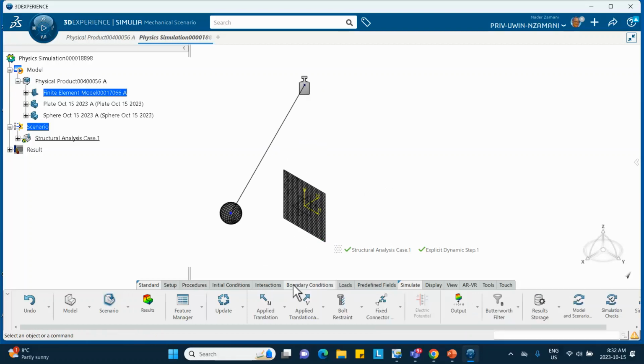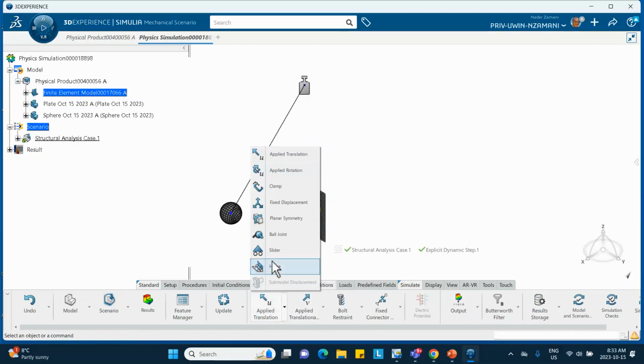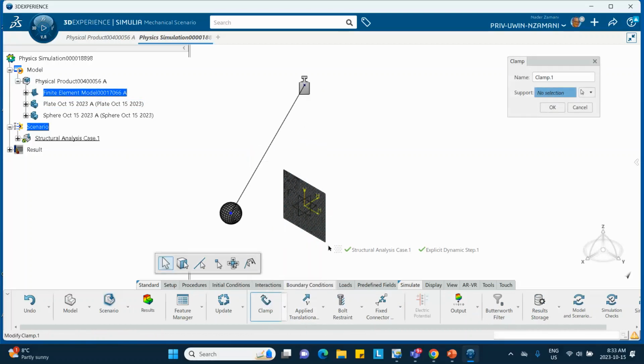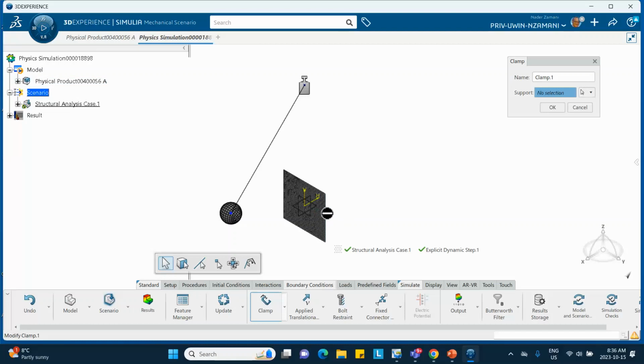The boundary conditions, these four edges are clamped, and I start picking these. It won't pick it. The reason is that that sketch that I drew in order to put this thing on it is showing. So I have to take these four edges.